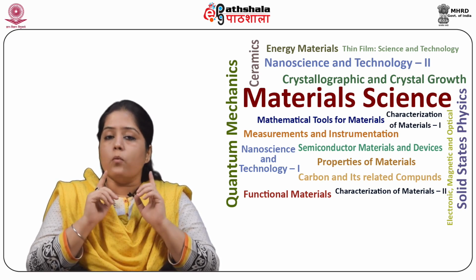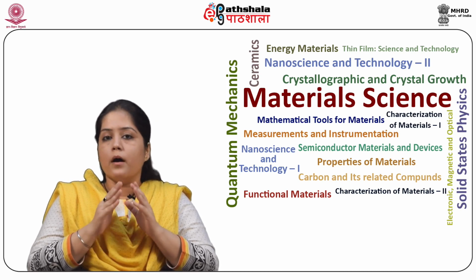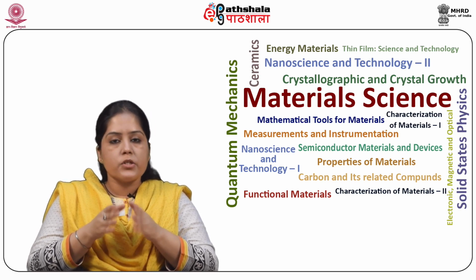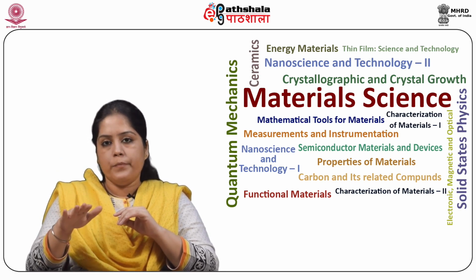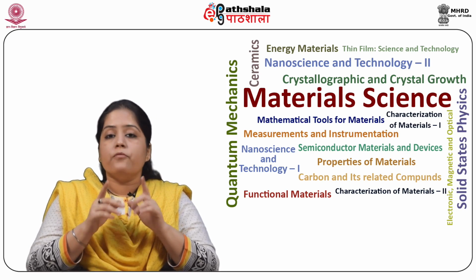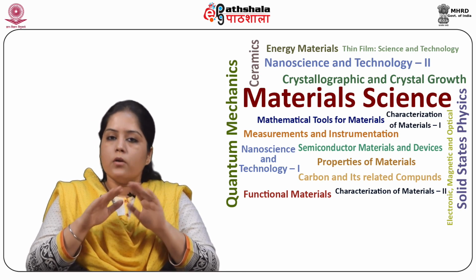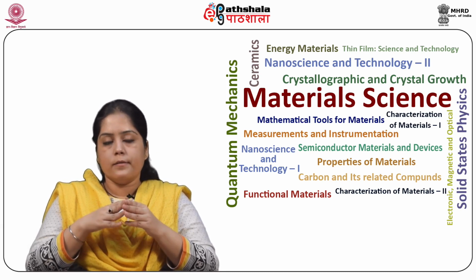6061 alloy is the most commonly used general purpose aluminium alloy. 7000 series are alloyed with zinc and they can be precipitation hardened to the highest strength of any aluminium alloy, with tensile strength up to 700 megapascal for 7068 alloy. 8000 series are alloyed with other elements which are not covered by other series, for example, aluminium lithium alloys.